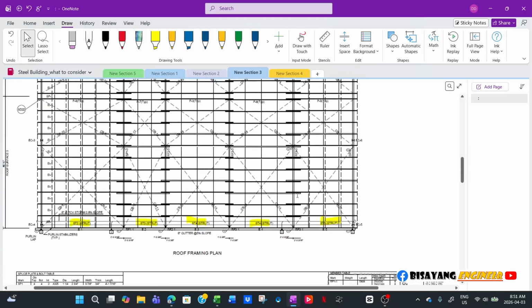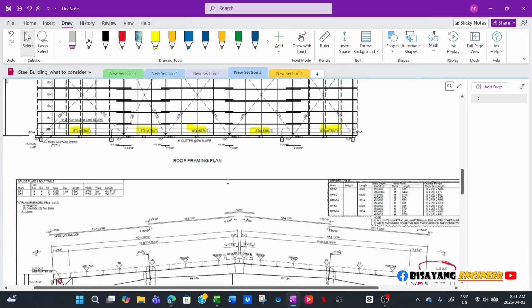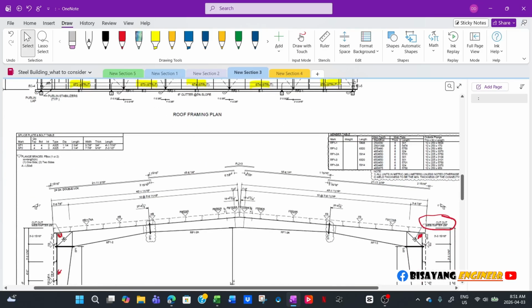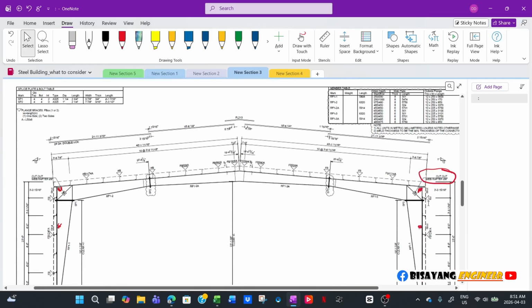So that's why the lateral load is higher. You can design bigger or stiffer purlins to transfer that load, but maybe in this particular application, the software realized that it's better to assign a strut rather than relying on the purlins.